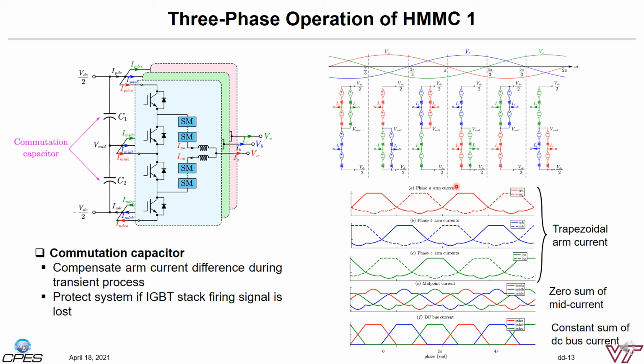As the HMMC arm output voltages are different, the current allocation of the arms is different as well in order to balance the arm energy. There are many arm current allocation options due to the freedom of the circulating current. As mentioned before, the selection of the arm current needs to make the total neutral point current zero all the time and ensure a smooth transition between upper arms and the lower arms when toggling the high voltage switching state.